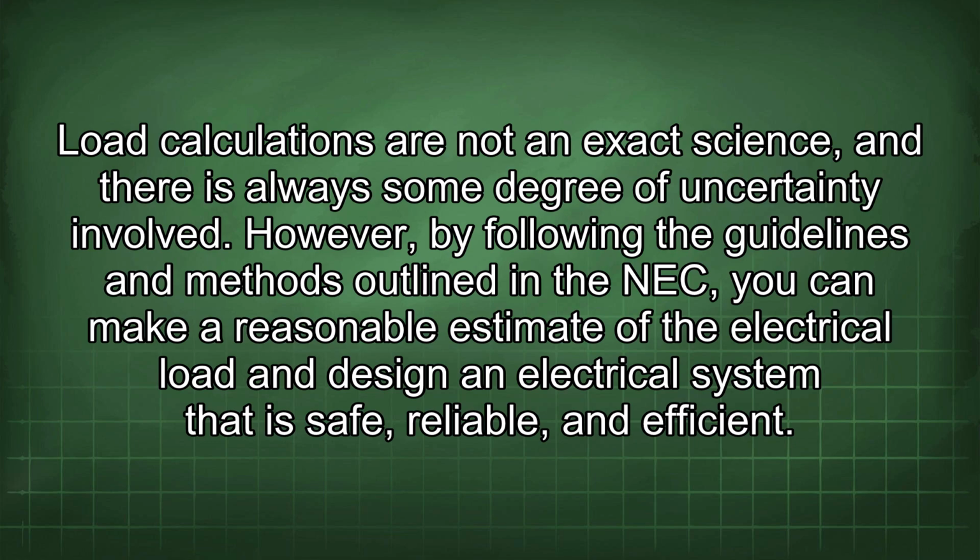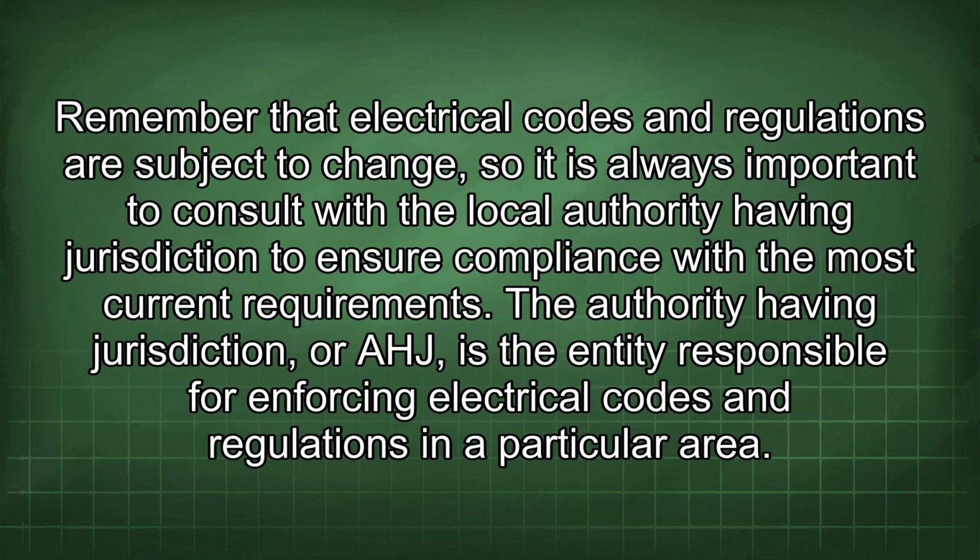Load calculations are not an exact science, and there is always some degree of uncertainty involved. However, by following the guidelines and methods outlined in the NEC, you can make a reasonable estimate of the electrical load and design an electrical system that is safe, reliable, and efficient. Remember that electrical codes and regulations are subject to change, so it is always important to consult with the local authority having jurisdiction to ensure compliance with the most current requirements.